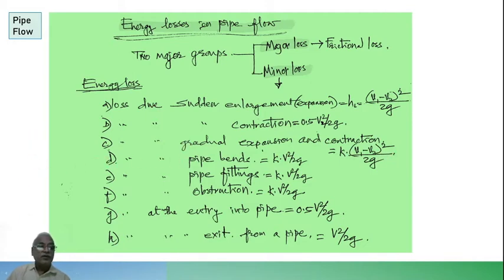Look here, what the terminology means is, there is a pipe coming, let us say, and suddenly the pipe diameter is increased. This particular case is known as sudden expansion. The flow is occurring this way. So it's not gradual, it is sudden. So that is the first case. There will be energy loss because this water tries to go that way and this tries to go this way.